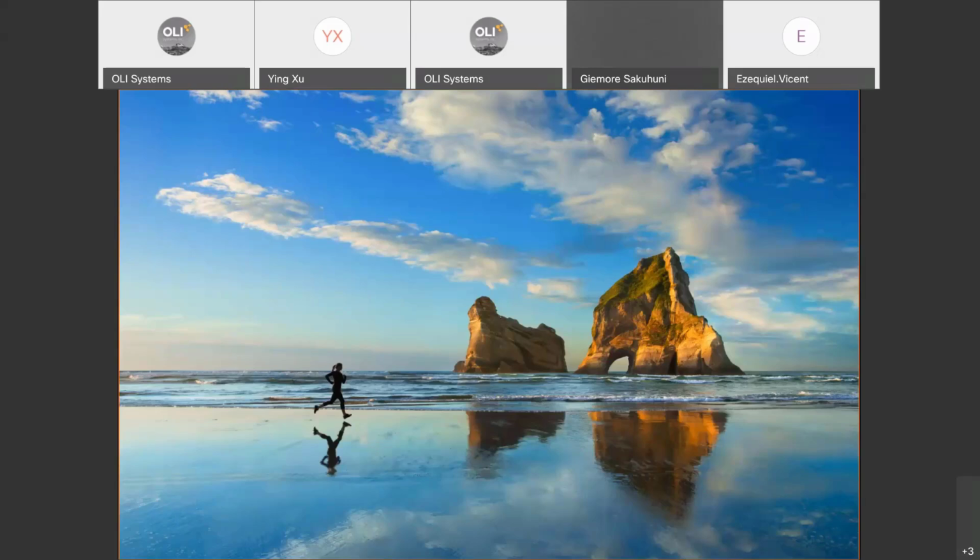Sorry, I cannot hear you clearly. Can you say hold the shift? Hold it the whole time, then double click on the icon of flow sheet, and keep the shift button pressed until flow sheet opens.